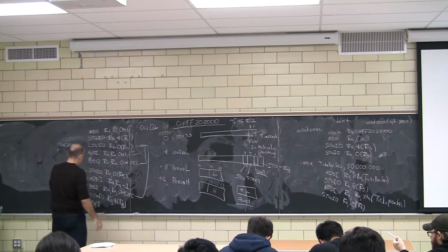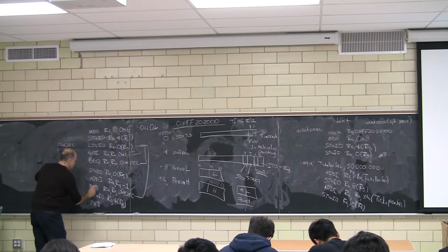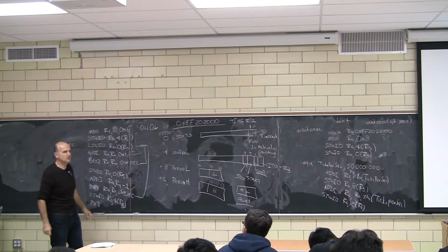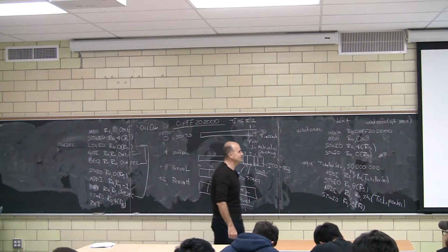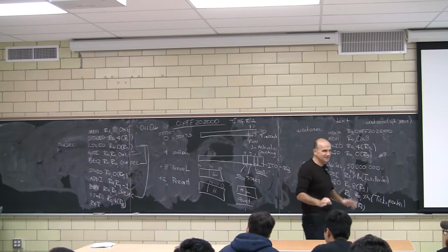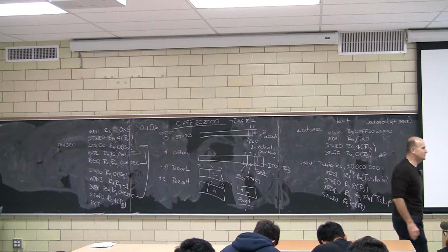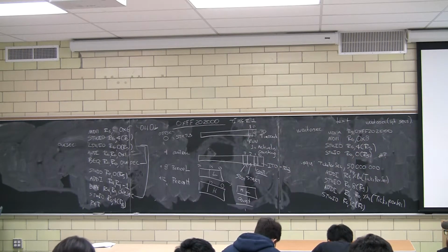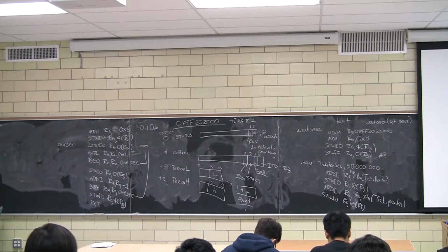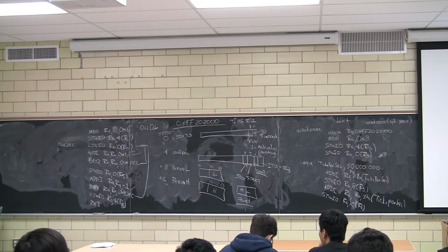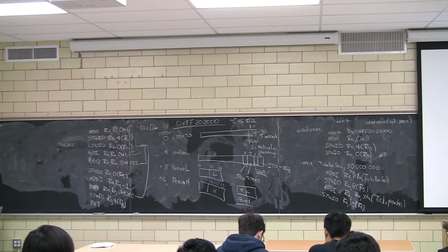Should that branch be non-equal, right? Start for 0, 1 sec? Absolutely. Because otherwise you're going to count 2 to the 32. Unless you call it with 1, you're going to count 2 to the 32, give or take seconds. And that's quite a bit of time. We're good? Okay, and that concludes the timer.